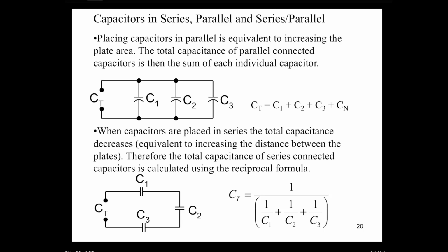And notice how this is again where we have our opposites between inductors and capacitors. A parallel capacitor connection is now one that's found as summing the values together, right? So we just take the value of one in farads, add it to another in farads, add it to the third in farads, and that's going to give you the total.